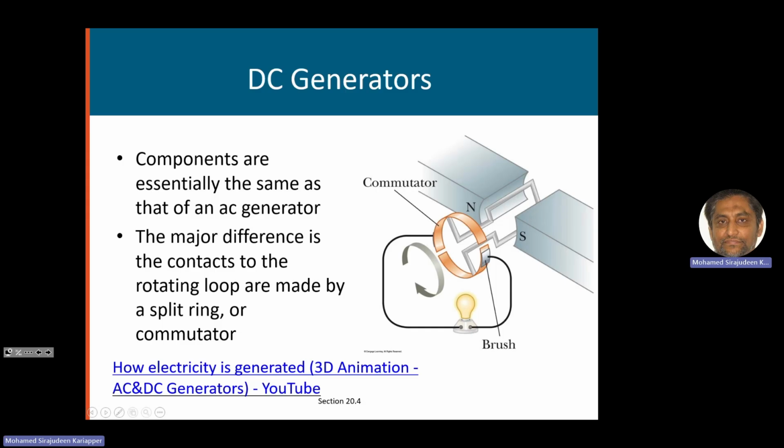So that is the AC generator. There are two rings, right? They are called slip rings. We need two rings to get the current out. And it will be AC, but that's not unfortunate. AC currents are sometimes more useful than DC current, because we can transmit a huge amount at high voltage over long distances without much loss, and it's easier to transport or transmit from one location to another compared to DC.